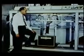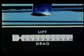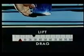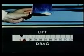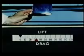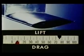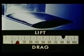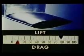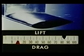We have suspended the first hydrofoil model from force gauges, which show us lift and drag on these scales. The flow speed is constant, and the gauges register the corresponding lift and drag. The ambient pressure is set at a level well above that at which cavitation can occur. We are going to induce cavitation by decreasing the ambient pressure in the test section, keeping the speed constant.